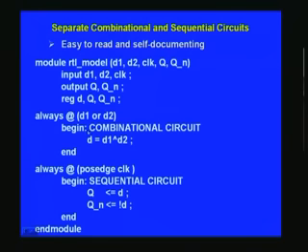And you notice that we have given a name here after begin. You are already familiar with begin and end. What has come as extra here is just a colon here and a combinational circuit name. That means whatever block you have here, you can give a specific name and perhaps call it later on when the need arises. Or you can just, for improving the readability, have this.